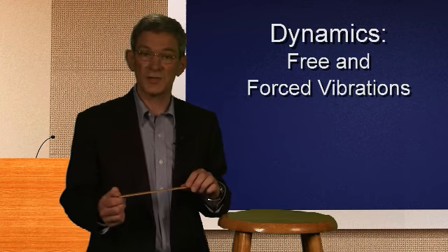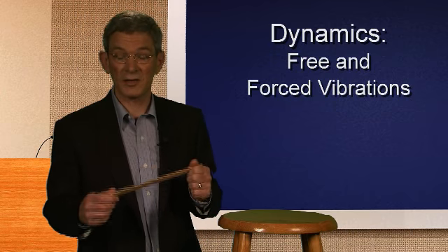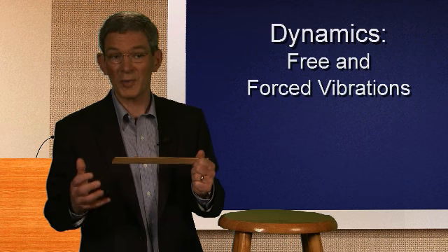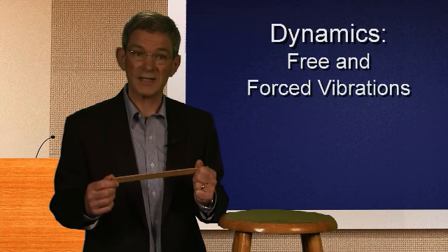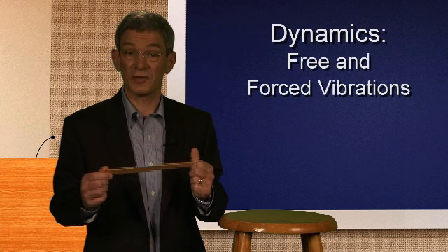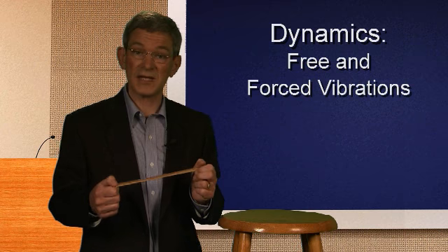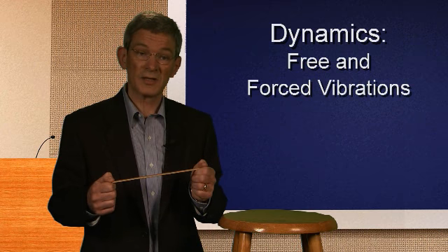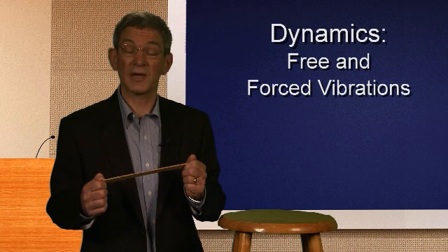Then you can invite the students to repeat the experiment themselves. And of course the class will erupt into a lot of noise and enthusiasm, and you've got them engaged. Then you can show students how to equate kinetic and strain energy to find the natural frequency of the ruler. And when you've done that, you can ask the students to repeat the analysis for themselves, but this time to use a whip antenna with a ball on the tip, so they can evaluate their own understanding of the topic.